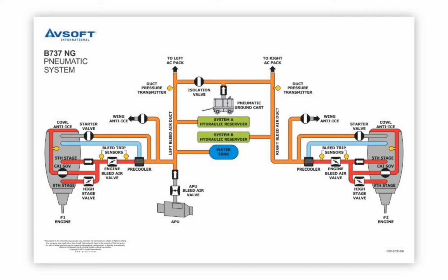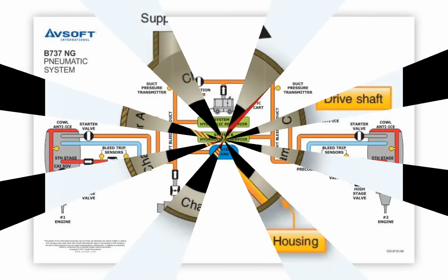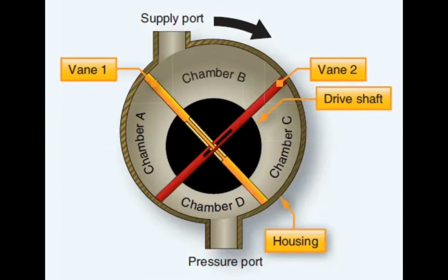What is the purpose of the relief valve in a pneumatic system? Protects against overpressurization. Thermal expansion, venting excess pressure overboard. What pump is most suitable for low-pressure pneumatic systems? Vane type.